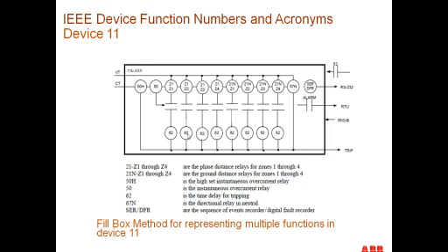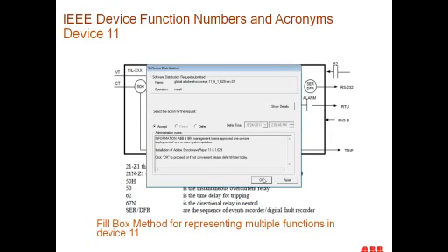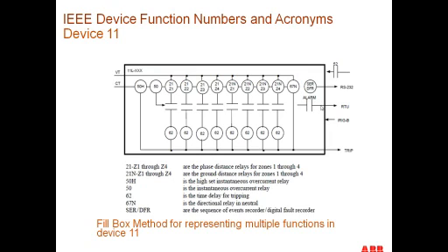Then the 62 relay happens to be, these are all timers. So associated with zone 2 and zone 3, we have a timer associated with them so they don't operate instantaneously, for coordination purposes. So here we see each of those defined. Then we also have other terms we define, such as SER for sequence of events recorder, and DFR, our digital fault recorder. All these are different types of relays, different types of parts of the system.